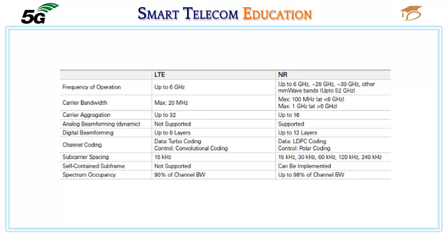The major characteristics of 5G Release 15 Phase 1 that enable eMBB, from 10 Gb per second to 20 Gb per second, include ultra-wide bandwidth, up to 100 MHz in less than 6 GHz, up to 400 MHz in greater than 6 GHz. Set of different numerologies for optimal operation in different frequency ranges. Native forward compatibility mechanisms. New channel coding. Native support for low latency and ultra reliability. Flexible and modular RAN architecture, split fronthaul, split control and user plane. Native end-to-end support for network slicing.